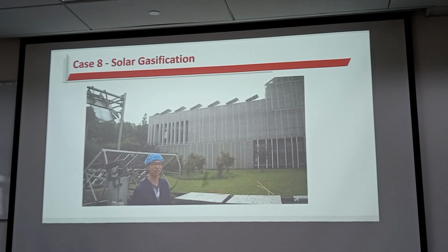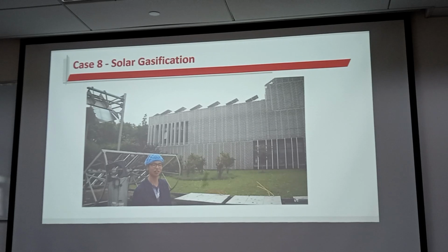Passive design is about getting a lower heat transfer coefficient of the building envelope, and using low carbon footprint construction materials, to lower the cooling demand and heating demand, and using lower air transfer to also lower the heating and cooling demand.